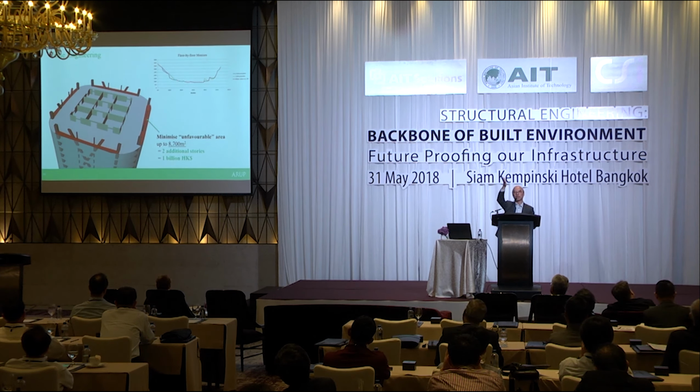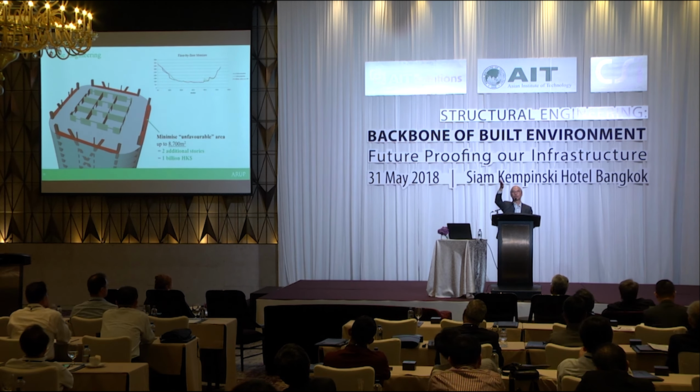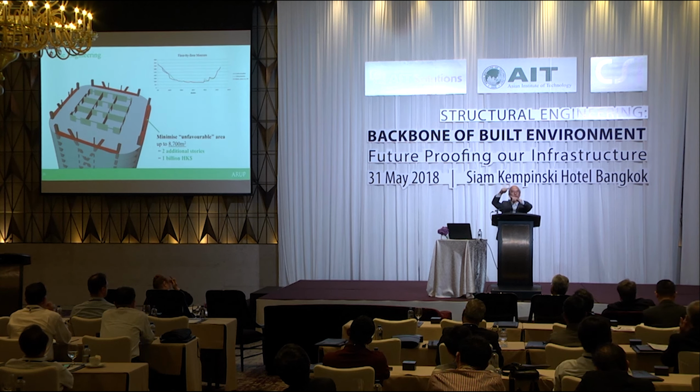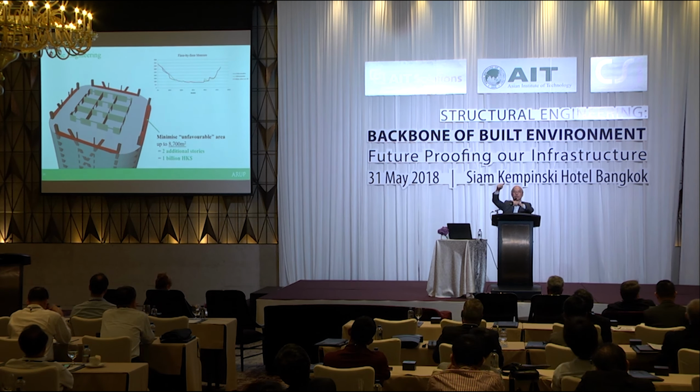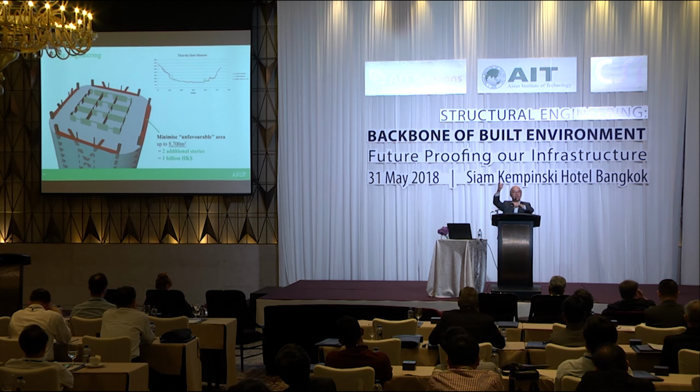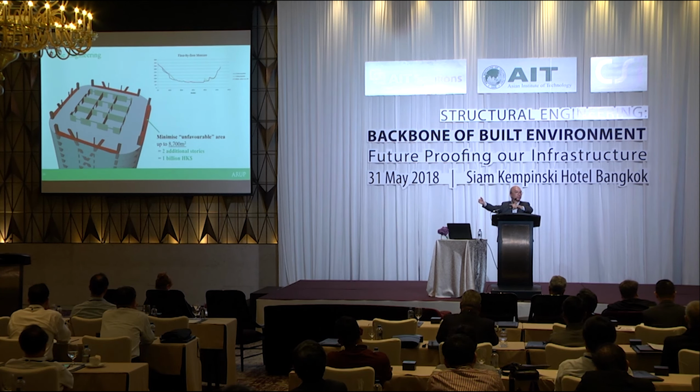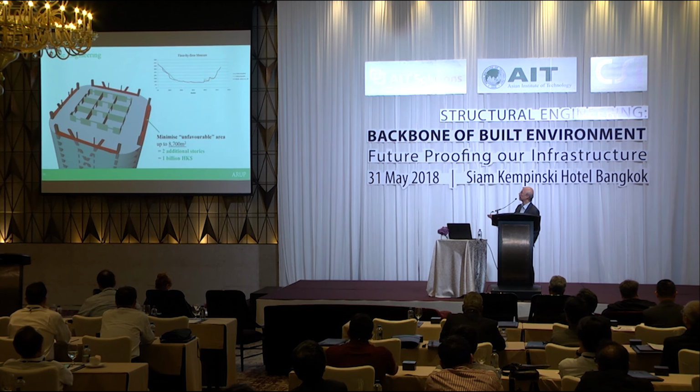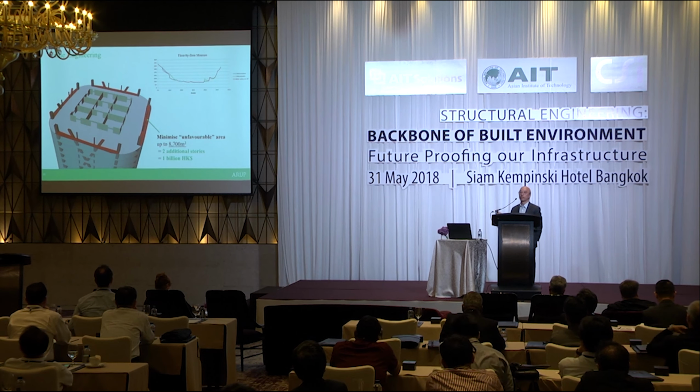Again, if you look at the tower, it is curved. That means if we want the bracing to be as close to the facade as possible, the bracing has to be split into a large number of levels, right? A lot of straight lines. But for bracing, we should make it as large as possible to make it more effective. That means if you have a large bracing, it's structurally effective, but you get more unfavorable area, right?